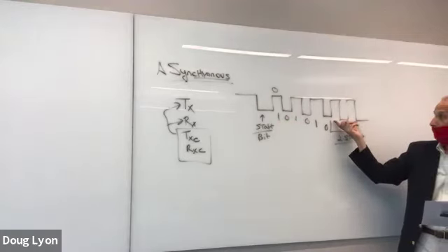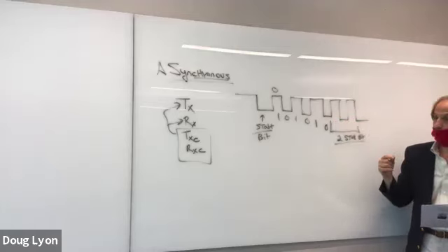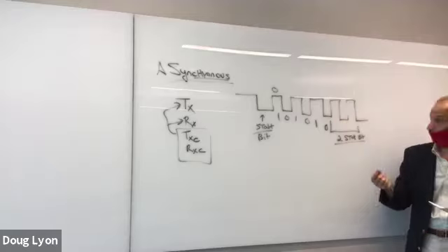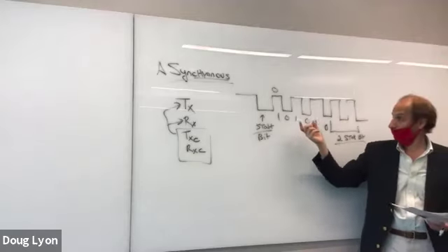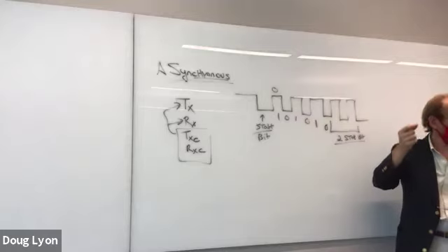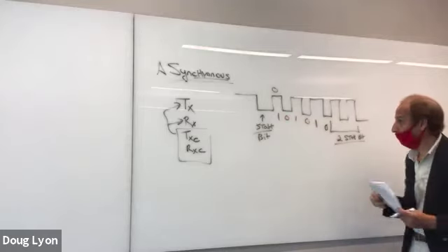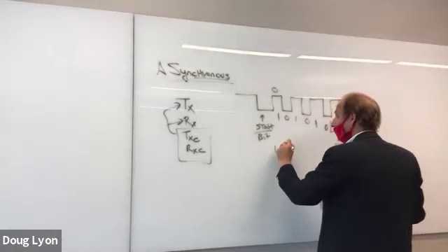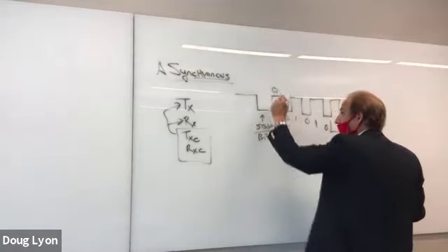These 2 signals coming together allow you to resynchronize the internal clock in your receiver. So your asynchronous communication interface adapter, which could in theory be built into your CPU, is effectively looking for these 2 pulses to come together so it can determine the timing. Because the most important thing that you must have here is a regular sampling signal that comes in, let's say, in the middle.